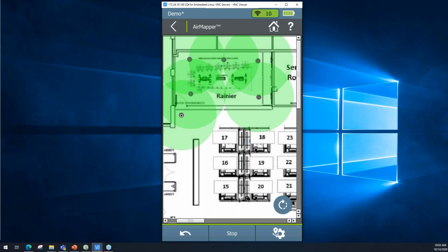So again, super important, like I mentioned earlier, make sure that for the size of the building, the propagation value you're using is correct. If you see that those circles are too big or basically covering the entire place, that may be a little too much. And collect the data as you move, a new data point every time you walk to the border of your propagation circle. And so on, you repeat. Pretty straightforward. Notice a little tip over here: if you tap on the wrong place, you can always undo using this little arrow here. And you have an infinite number of undos, so you can keep undoing and undoing if you want.